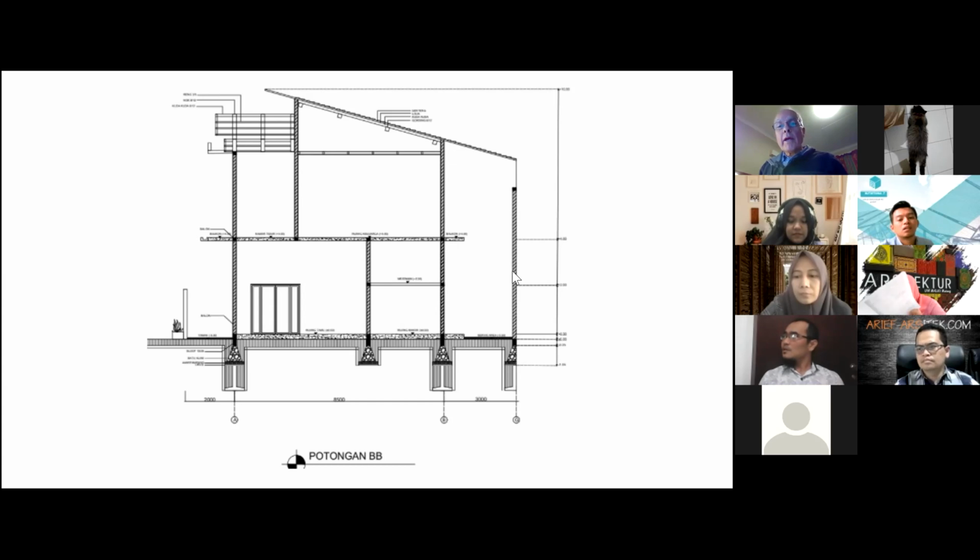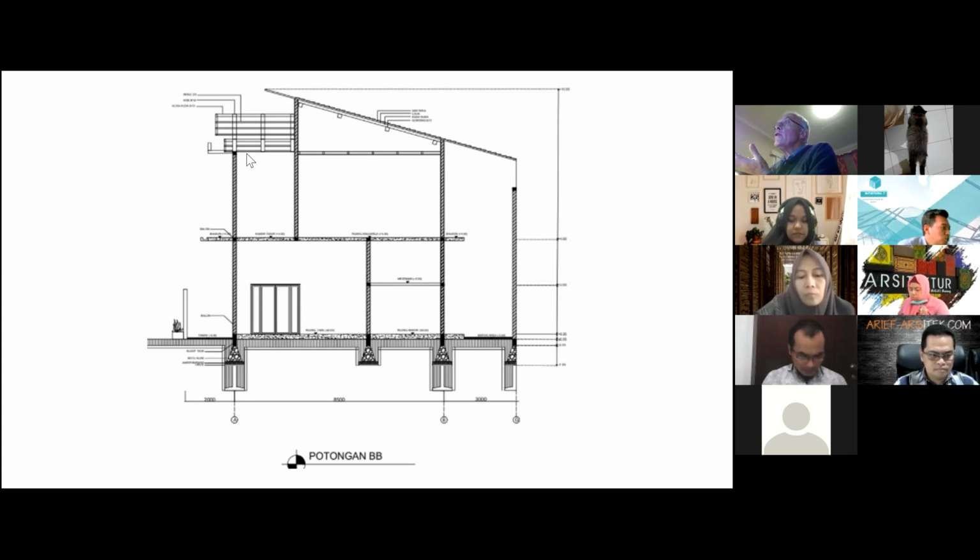So at each level in a building, we must have a sort of diaphragm to tie the building together at that level. Like at lantai dua, the floor slab ties everything together very nicely. It acts as a really strong diaphragm. But at this roof level here, we need a series of tie beams to create ring beams, a ring beam that will tie and stop the building shaking apart at the roof level. So those are the improvements that we would need to make to this design.